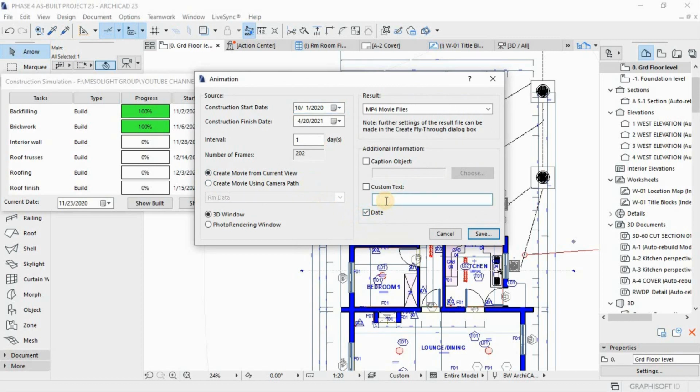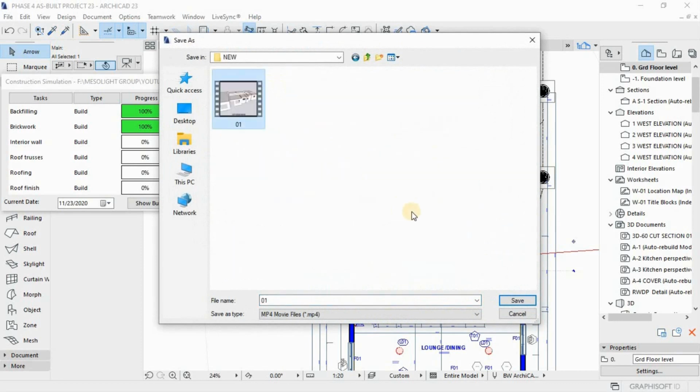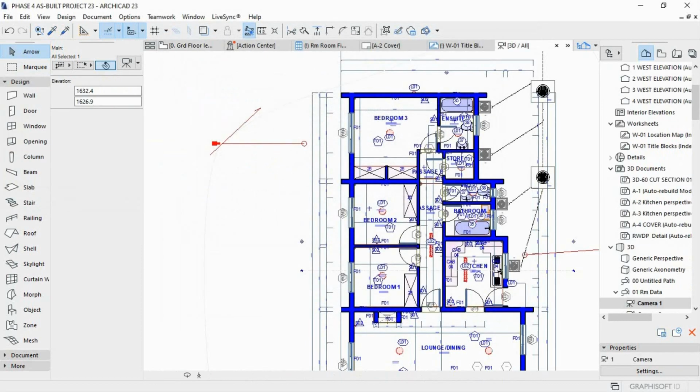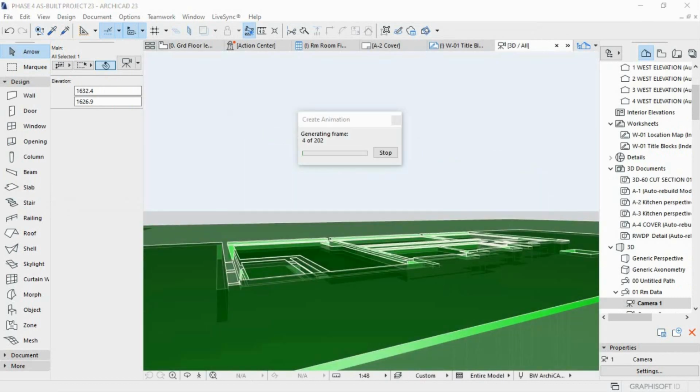Here, individual building objects and components are intelligently linked with the project construction phases, resulting in a complete image of an overall project planning. It could be an image, a Gantt chart, or a video presentation. Here you can be flexible, depending on the skills of your department, your office. In ArchiCAD, we call it the construction simulation.